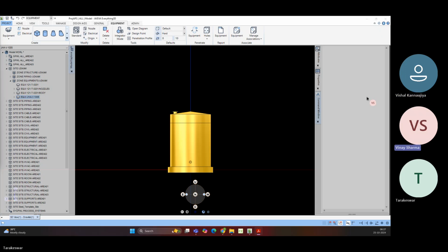In that, there are also high pressure vent and high pressure drain. Vents are always at a higher position and drains are always at a lower position. Just remember this. The drain and vent will be provided by the process guy, or the stress guy. Temporarily you can put them anywhere, but later he will tell you that you need to give a high pressure vent or high pressure drain. Understand? Any doubt in this?